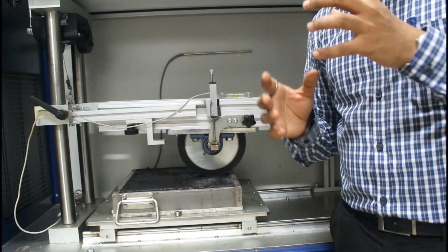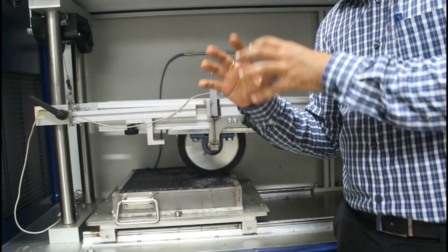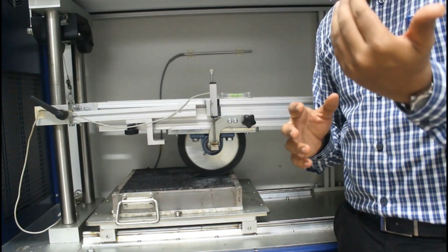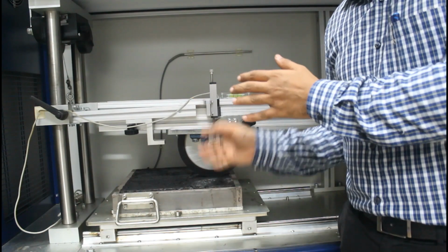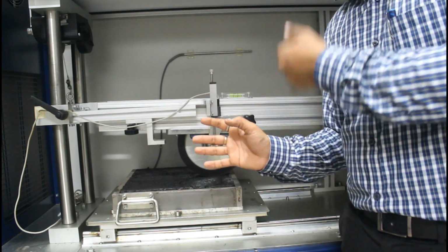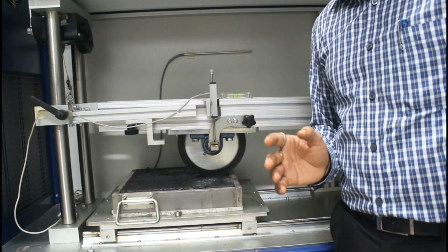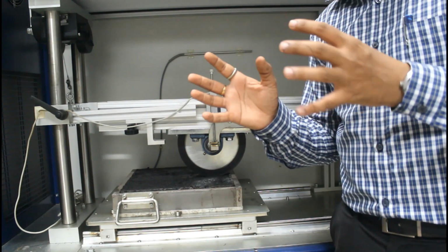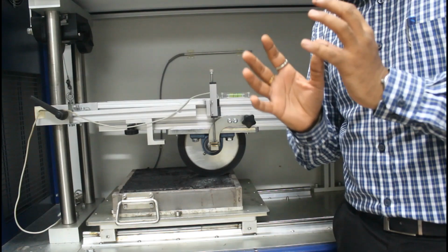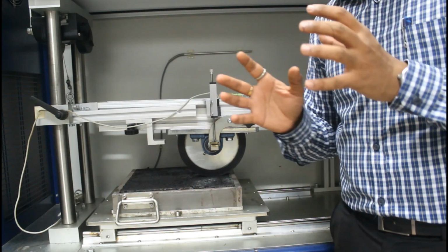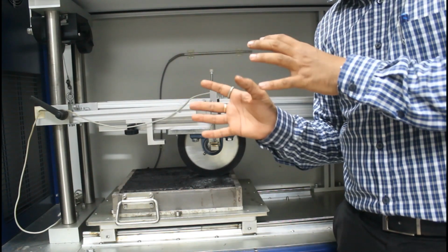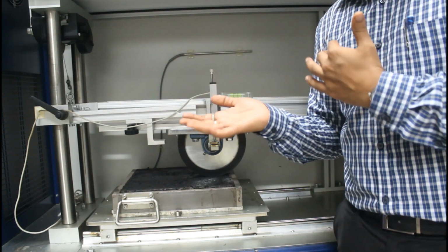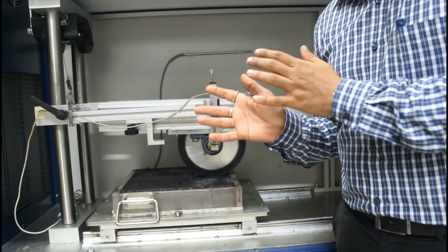So further, let's say if you want to compare this with the field rutting, there are many studies where they try to correlate, right? If this is 2 mm for this particular number of cycles, what would be the expected rutting in the field for a given traffic level? There are many studies where they have performed this kind of correlation as part of developing guidelines. So this way, this equipment can be used to study the rutting behavior or to correlate the field performance with the lab performance, right?